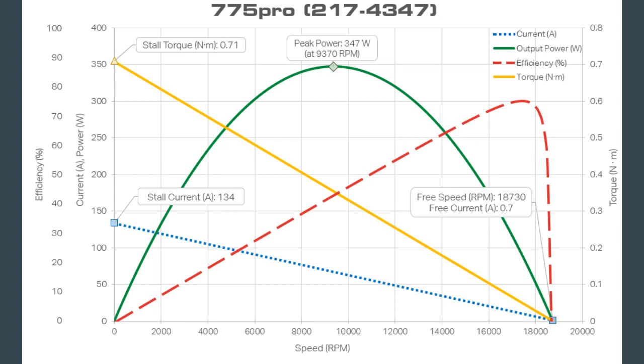The way that we tend to do things is we just pick a gear reduction that's close, and then we try a whole bunch of things. We're like, oh, we need it to be slightly faster. Let's see if changing the gear ratio helps. And if it doesn't, then we might add another motor. Because this is kind of complicated, we don't really hone in on all of the details. We just come close. So this one already had dimensions.